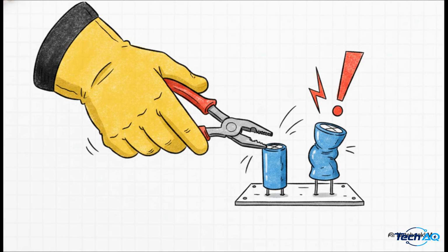But listen, because they hold energy like a loaded spring, and because they can actually hold that charge long after a device is completely unplugged, safety is absolutely paramount here. You have to always discharge a capacitor before you handle it. Never exceed its rated voltage, use insulated tools for sure, and always double check your positive and negative connections if they are polarized.